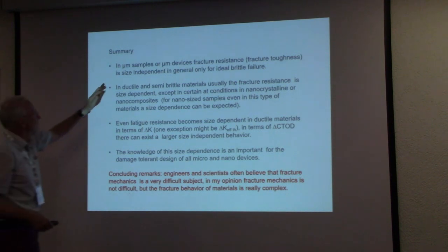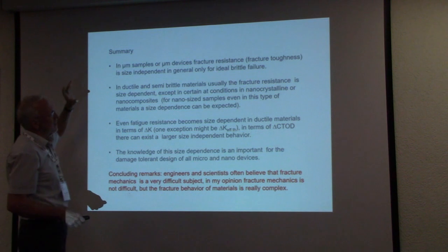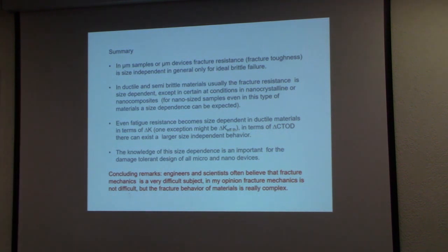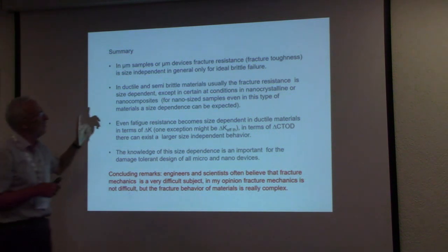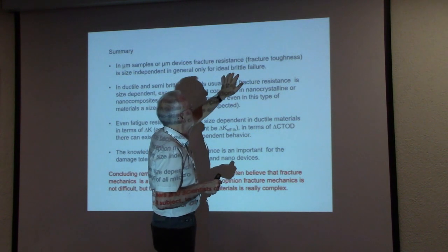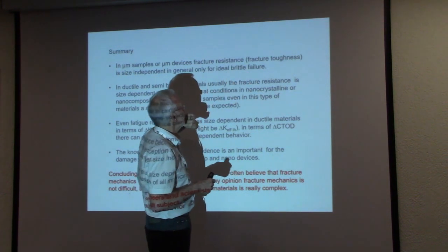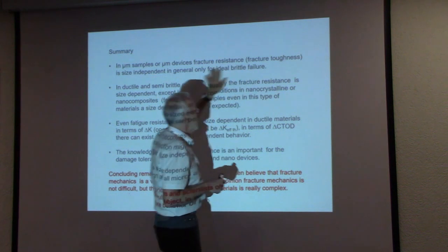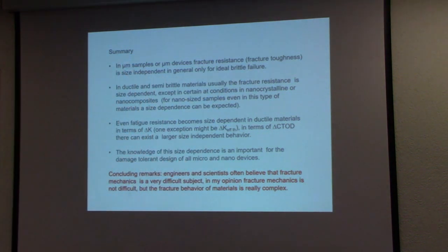In order to summarize the things, in general, if we have samples with micro dimension, the fracture toughness is only size independent if it is a material characteristic parameter for ideal brittle failure. And in some cases it can also be a material parameter, but then you have to fulfill all the requirements which we also have in macro samples.